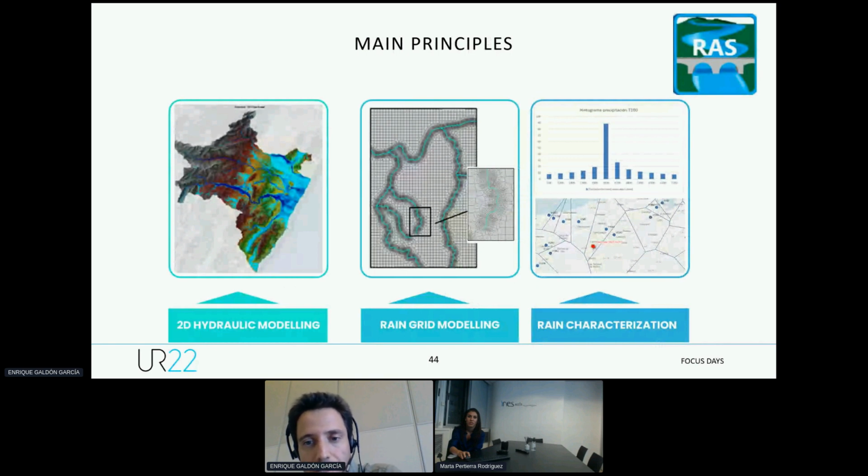So what we did is first of all define which are the critical rains that are going to be affecting our railway network. And for that, what we did is cut the railway network with our rivers and define the concentration times and search, in the case of smaller watersheds, peak intensity diagrams for defining the precipitation. And in the case of the bigger watersheds, we were going more to a homogeneous distribution of the rain, due to the area that is covered.